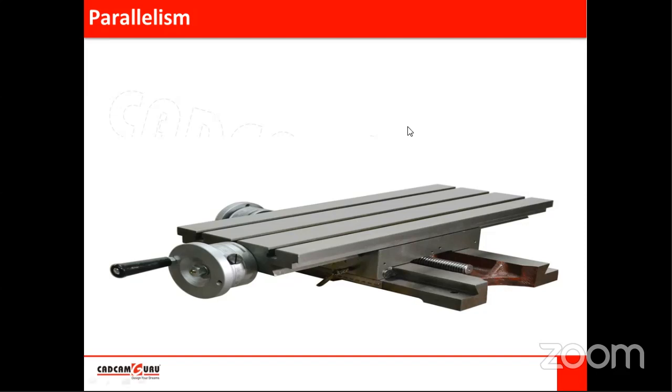So opposite faces of the drawer, or the cavity inside the table, so opposite faces of that cavity, they should be parallel to each other. Okay. So I'm not talking about the surface of the drawer and the surface of that cavity. You can apply parallelism between the same component, meaning two opposite faces, two sliding faces of the drawer, or two opposite faces of the cavity. They should be parallel. Okay.